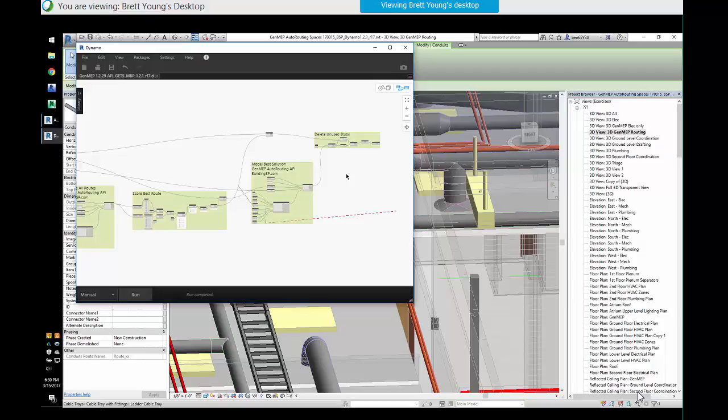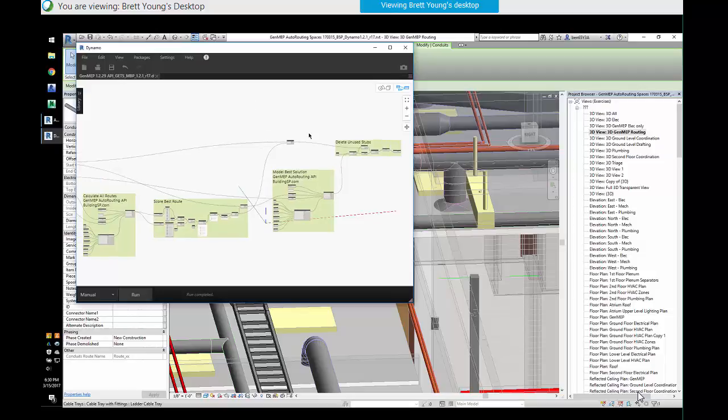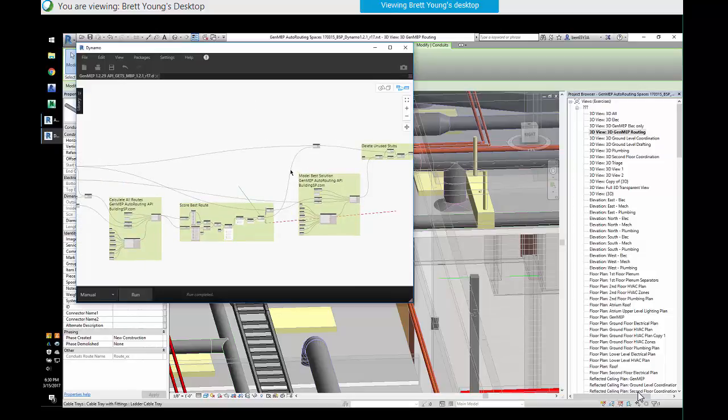So I have 3 different MEP Dynamo workflows that I have been using recently. This specific one, I think we can really get ahead and put small electrical systems into a building much earlier than normal, because it doesn't take a lot of time to actually manually detail and draw these things out by hand and then have to fix it when other systems move, right? So you can actually run the simulation, put in your routing, and then next week when everything changes, run it again and figure out what the best solution is, and just have the solutions put in the Revit model as opposed to having to fix it every time and waiting until everything is more set in your models to actually model that MEP.